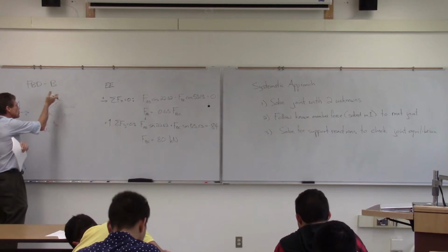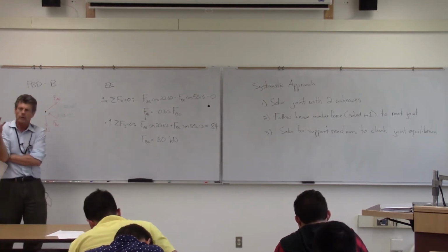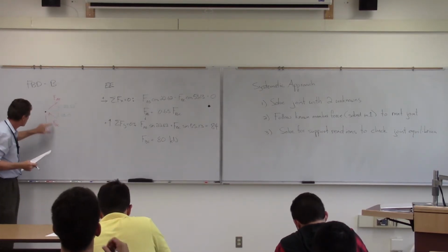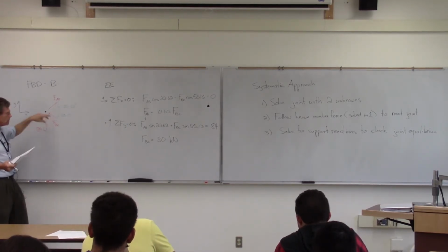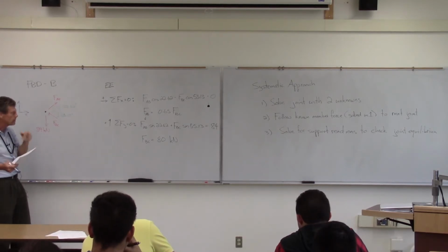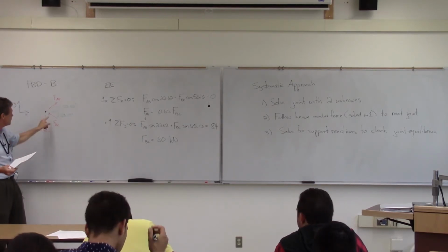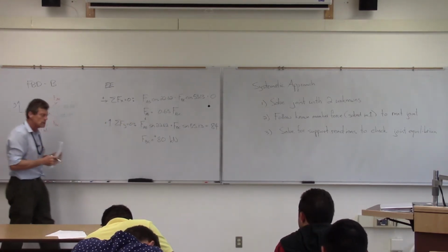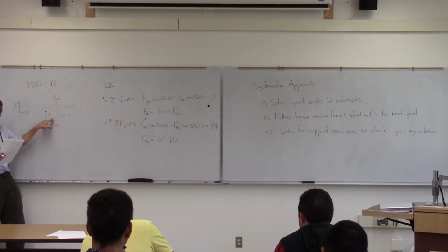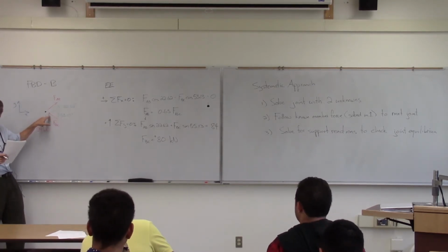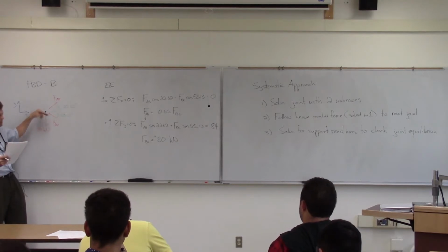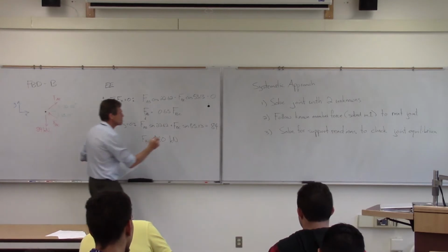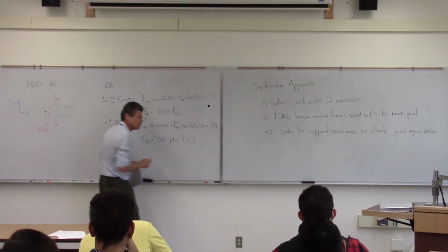Well, we kind of know the direction here. What we're going to be asking for you in the truss analysis is, is this member in compression or tension, based upon the way I solved it. So it came out as a positive quantity, right? So that means my arrow's in the right direction, right? So what is it doing to the joint? It's pushing on it. So what's it going to be doing to the member? In reverse, it's going to be pushing back. So we'll report that then as compression.